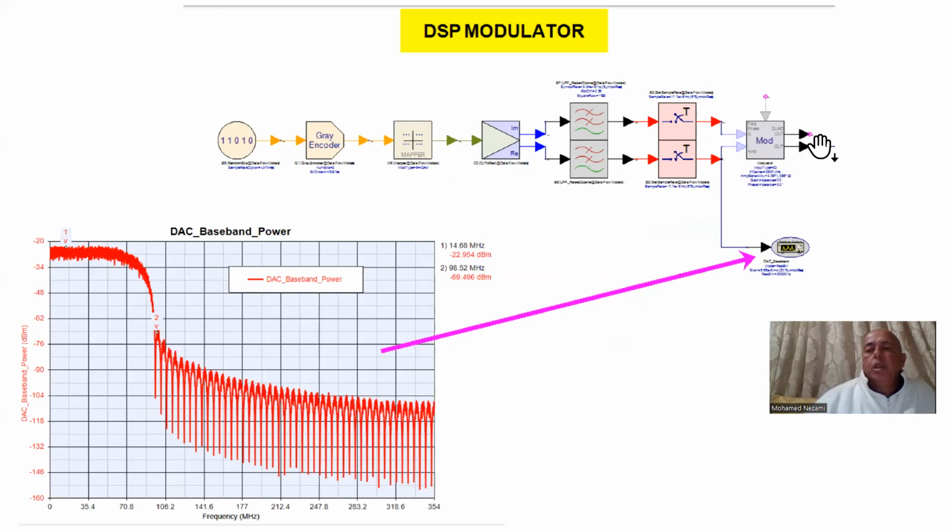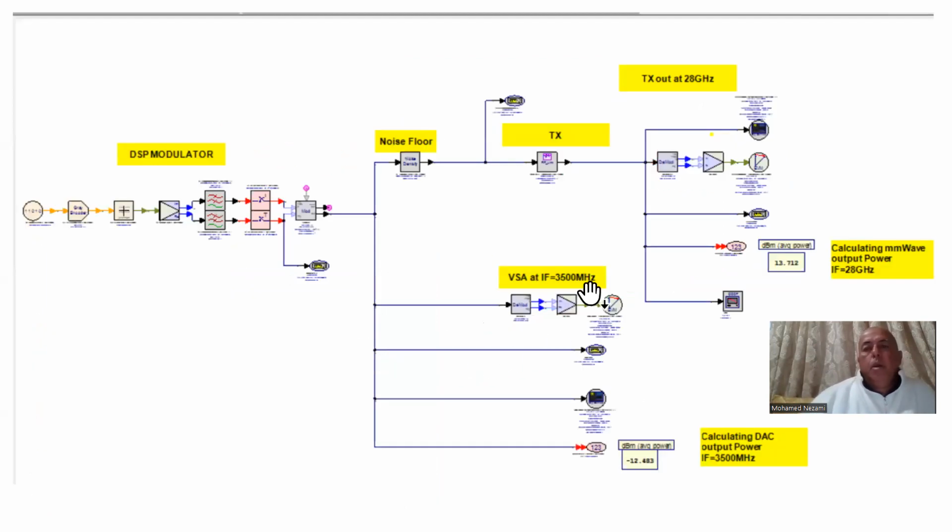So this output here is baseband, of course, but this output here is at 3.5 gigahertz. And you can see here's the baseband signal. Right now it's 100 megahertz, which is half of the channel. This is the imaginary only, not the real. It's one leg. And the other leg is the same thing, spectrally inverted, and you get twice that, which is 200 megahertz. So this is the system in here.